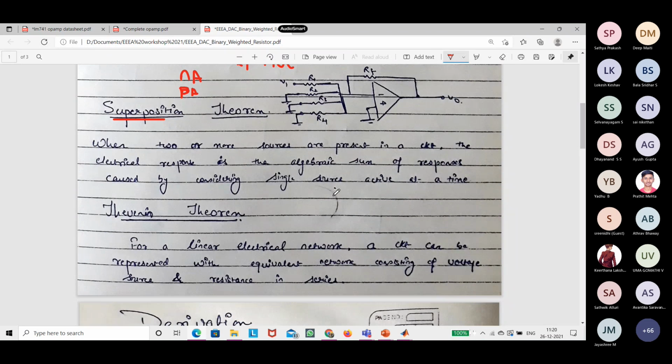So say you have a circuit that has a voltage source V1, and then there is another one having V2. Instead of solving this circuit as a whole at a time, you just take V1 at a time, short circuiting the V2. That is how you disconnect the V2, right? Then suppose I have to take V out across this resistor.